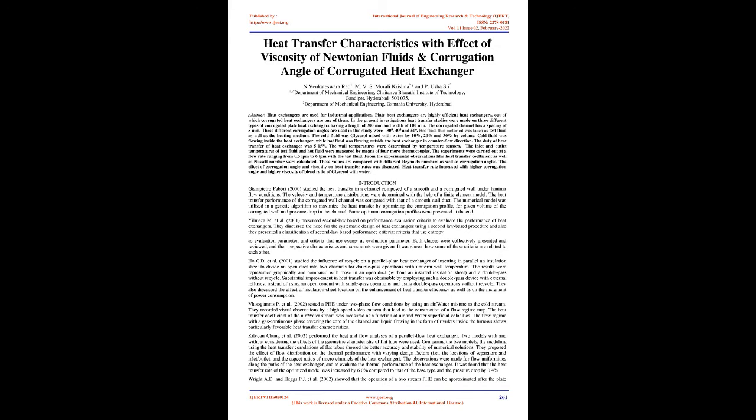Substantial improvement in heat transfer was obtainable by employing such a double-pass device with external refluxes, instead of using an open conduit with single-pass operations and using double-pass operations without recycle. They also discussed the effect of insulation sheet location on the enhancement of heat transfer efficiency as well as on the increment of power consumption.